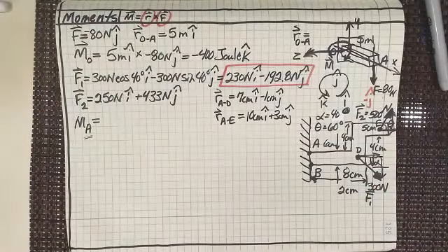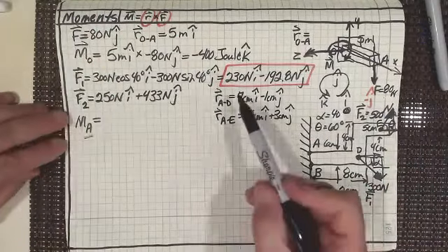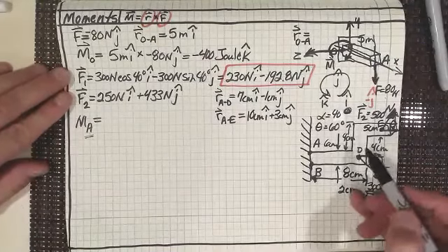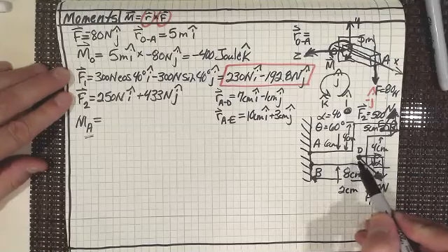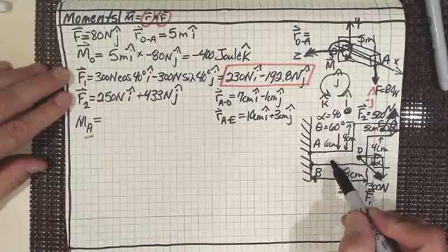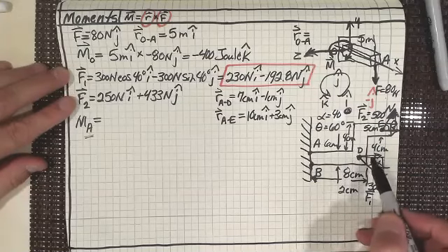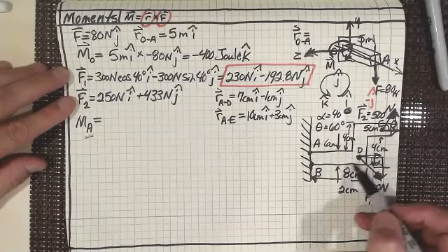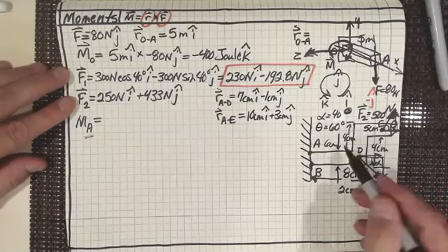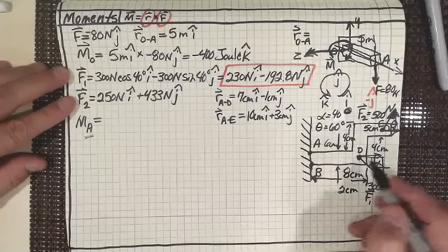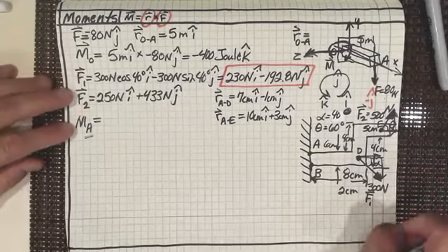Does everyone see how we got those distance vectors from this diagram? I've used these individual quarter-inch squares as 1 centimeter, so you can see I've drawn to scale this flange coming out and the 2 different cables attached to the flange in those 2 different directions.